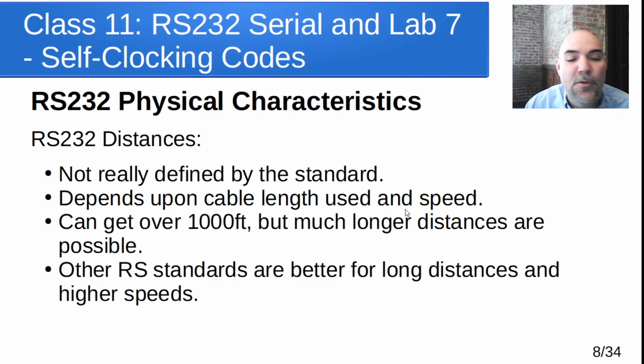But if you need longer distances than that, there's some other standards that are part of the RS set of standards that we're going to look at here in just a little bit, that are a little bit better for longer distances and higher speeds. RS232, though, is simple, and it's been around a long time. A lot of PCs and servers still have RS232 ports on the back. There's a lot of industrial equipment that still has RS232 ports on it.